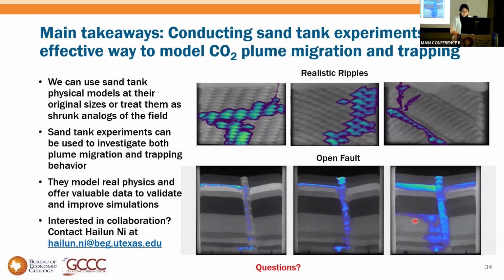And finally, for the injection scenario, the rate that we use here, and also according to the interfacial tension and the grain size, we also calculate the capillary number, which represents the force ratio between viscous forces and capillary forces, and also the Bond number, excuse me, which is the ratio between buoyancy forces and capillary forces.